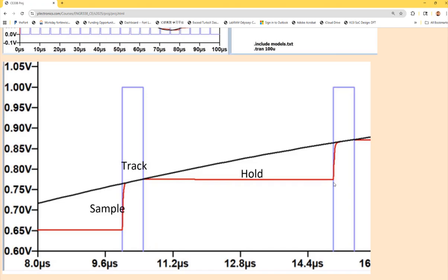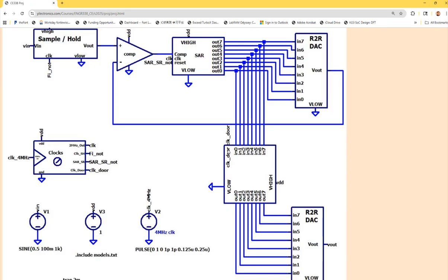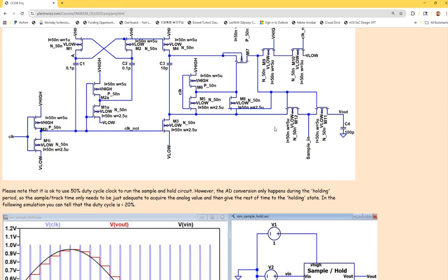And then whenever it's done, you kick those 8 bits out by using this flip-flop array, right? There will be a clock like this one. I call it the door clock, like a door. You kick it out from the door, and so it's available to the outside. It's basically just an array of flip-flops, right? All the data is on the D side of the flip-flops. Whenever it's ready, you send the clock to the flip-flops at the same time. So the output will be the final converted result instead of all the intermediate states of the SAR diagram. Does that make sense? So that's the entire workflow of the SAR ADC's circuit.